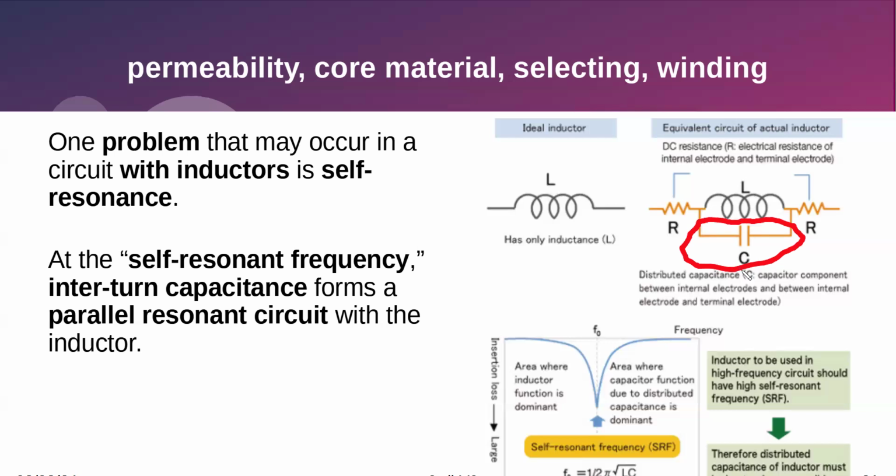It usually limits the upper frequency range you can do for a circuit, because in the case of the parallel, when it starts to resonate, it becomes a very high, almost infinite impedance. And I said there was no formulas, but there's one down here. You remember that from last week, right? This guy.